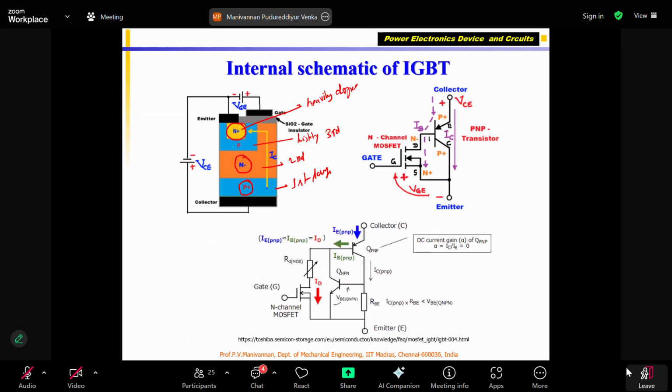For N plus, instead of 50 or 20 phosphorus atoms, you would have added 200 phosphorus atoms. That means 800 will be silicon and 200 will be phosphorus. That means 200 additional electrons are available. So the conductivity is very high.